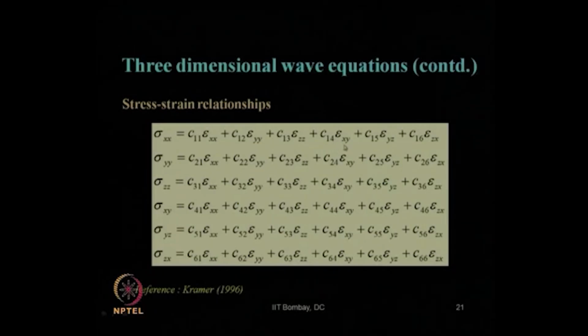This modulus is related to the shear, because it is relating to the shear strain. These are relating to the normal strain. So, basically, with the other 2 shear strains, all these modulus coefficients, that is stress versus strain, can be easily written in the form of a matrix. That is what it shows, right.